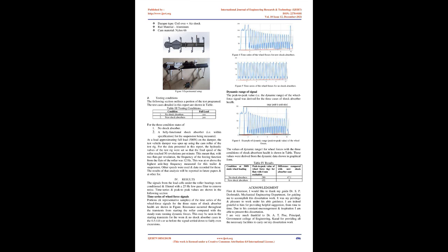3. Experimentation. Vehicle suspension testing machines are generally configured as 2 or 4 rollers in a rigid frame. The wheels of the vehicle under test are placed between the rollers. For normal operation to test the suspension on a vehicle, the vehicle's wheels are spun under the power of the tester. The speed of the test vehicle is applied. A dynamometer then measures whether the retardation force present from the speeding effect of the test vehicle's wheels is adequate.